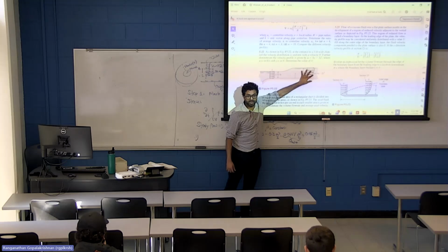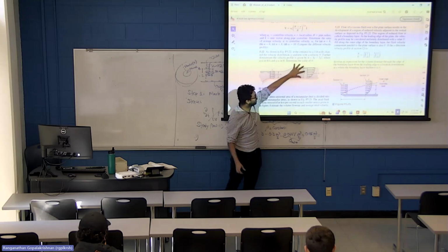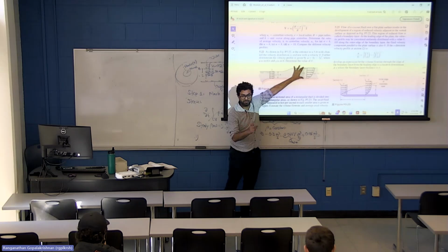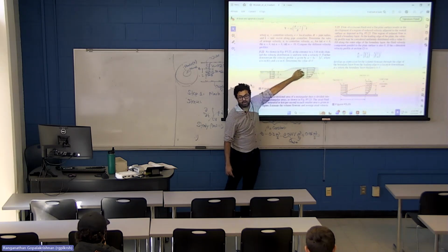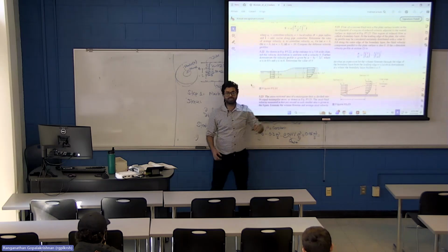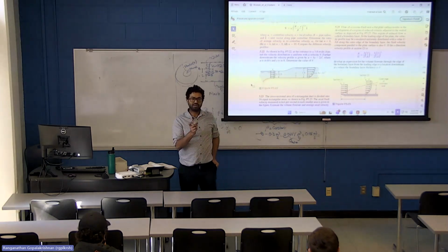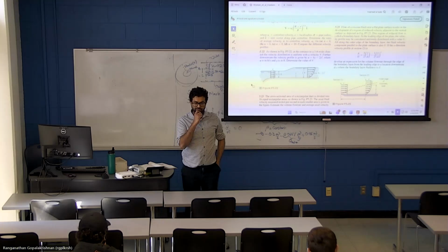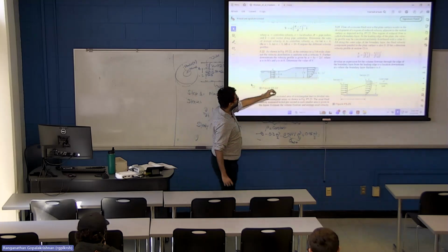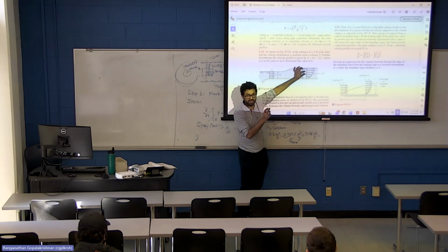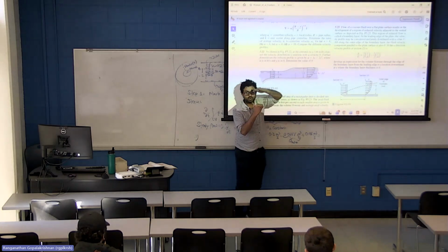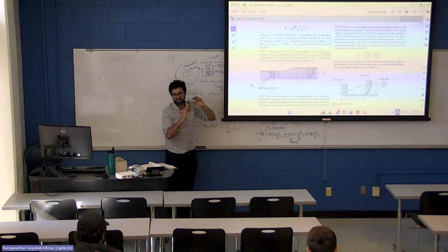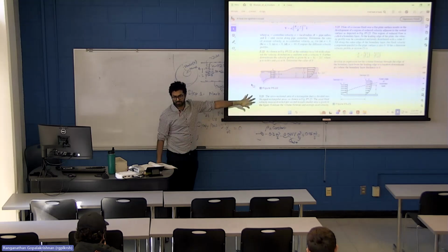So 3 times 0.75 times v should be equal to the flow rate on the other side, which is the velocity multiplied by area. Except this velocity is not uniform, so you can't just multiply velocity and area. You have to integrate along the height. So what is the area of this channel? If you express it in terms of elementary area, dy times what? It should be dy, a small length, multiplied by the width, which is uniform. W times dy, right? So you integrate this velocity over the height.